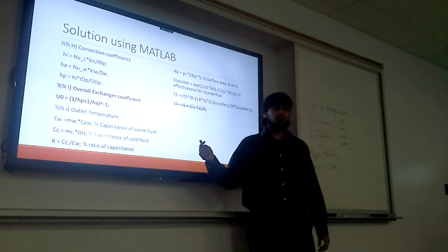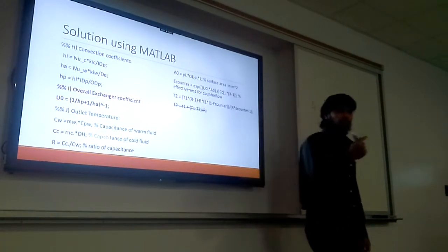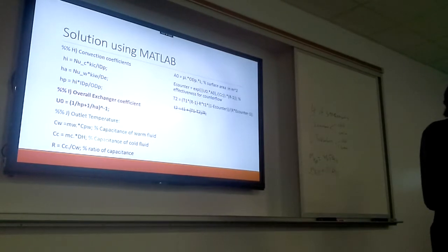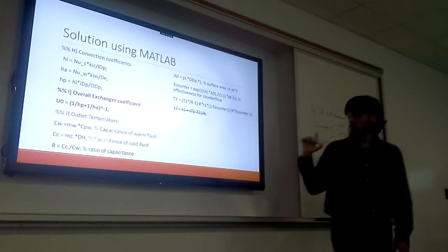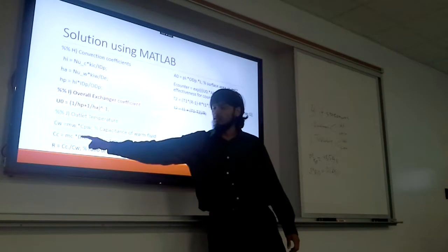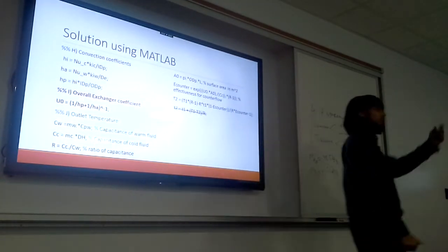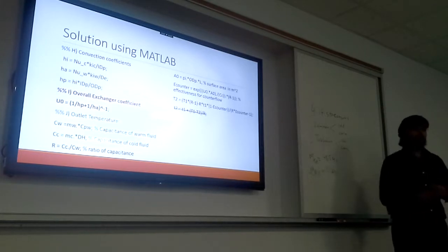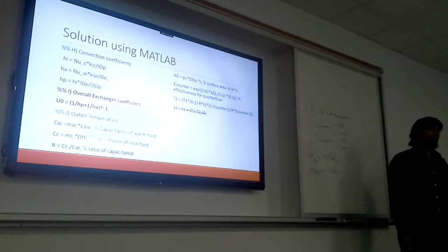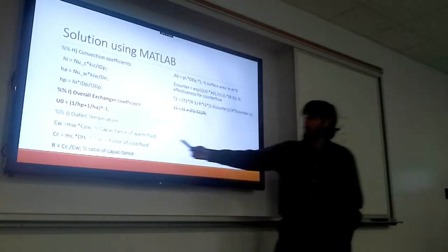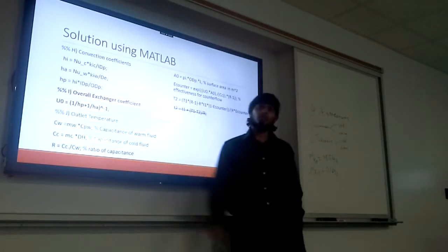Is it vapor to liquid or liquid to vapor in the problem? Liquid to vapor. So if it's going from liquid to vapor, all you account for is the heat of vaporization, h_fg. And that's where this comes in handy. The enthalpy of vaporization is where you apply this value. Okay. And obviously we don't need it for the water, because there's no phase change for the water.